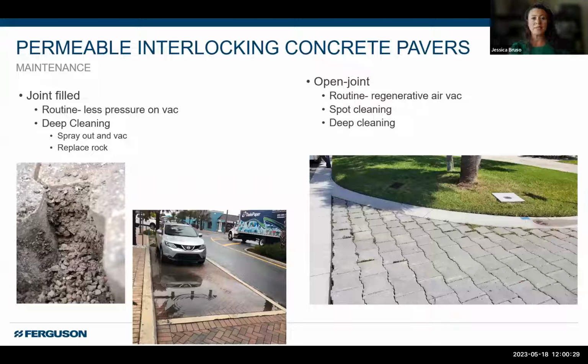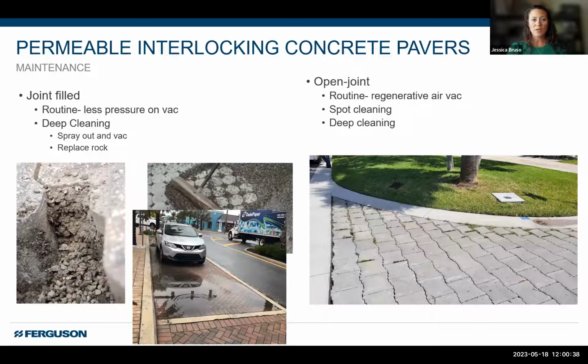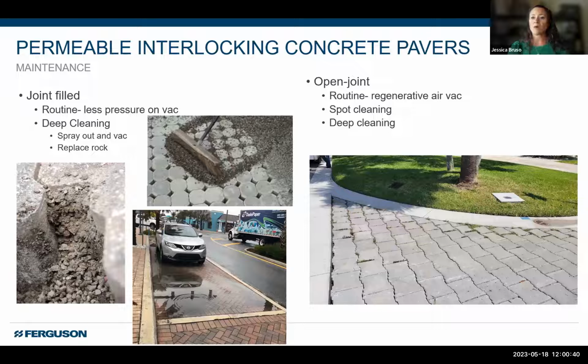As far as deep cleaning, and this is what would have to happen, say in this case here, we can see that ponding. You actually have to spray out all that gravel, back it up. So that's basically good as new. You just have the paver sitting there, and then you have to sweep back in more of that gravel that's necessary. Okay, so there's that extra component there. So it's not just removing what's there, but also putting in new gravel, so you have those joints filled and that stability again.